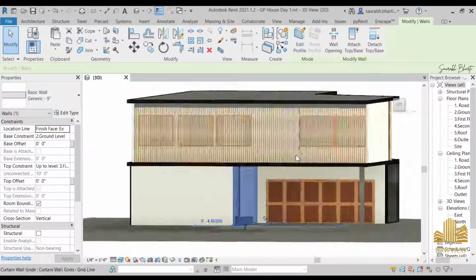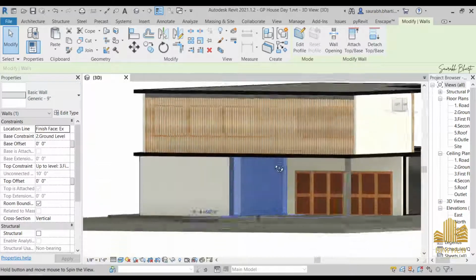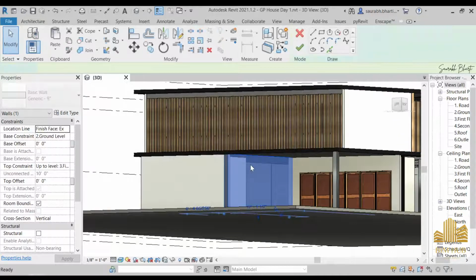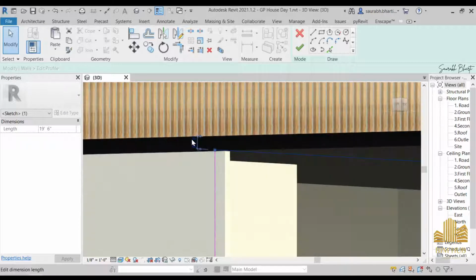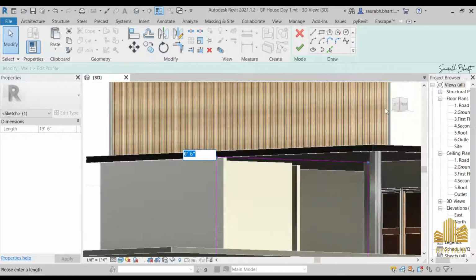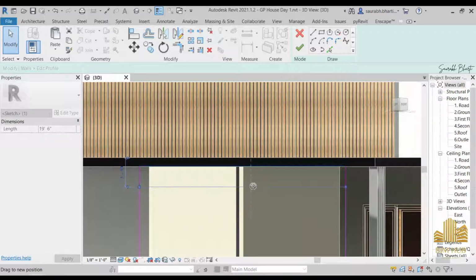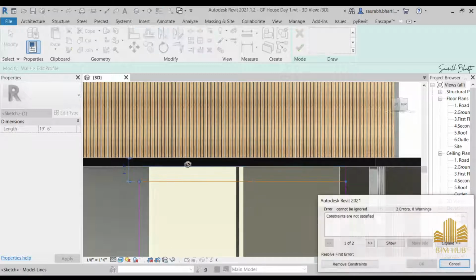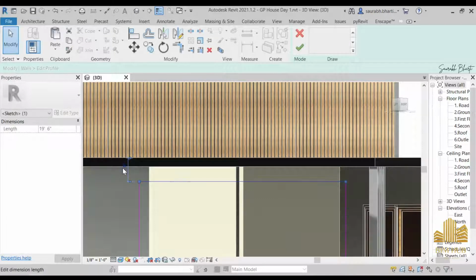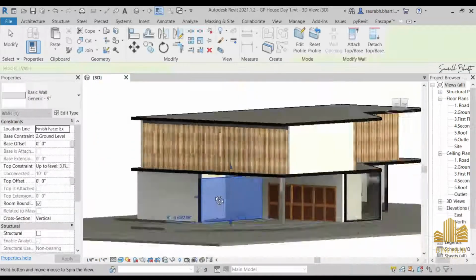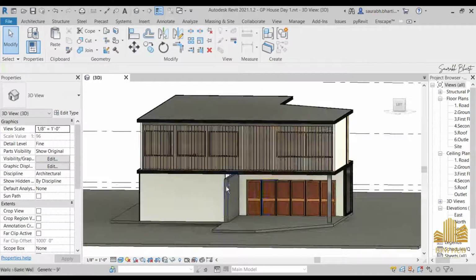it is just a connected wall. So go to edit profile and select this one, and right now it is at 0.6. Okay, what if I reduce it, we have to reduce it by 9 inches or 1 foot. So it was 6, and we can keep it at 1 foot 6 inches. So just remove the constraints, and here you can type also. So at this place, and a joint element, and now we have 6 foot wall, I mean 6 inches wall.